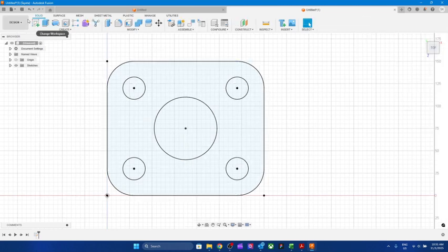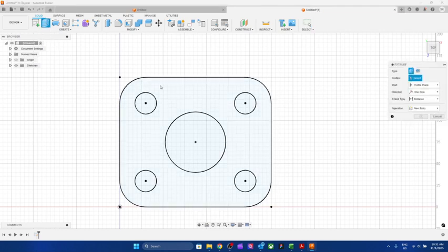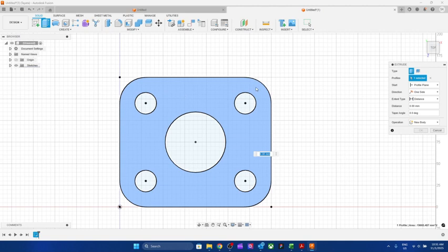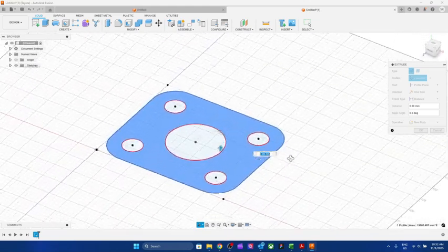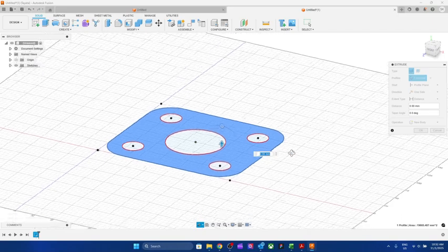Now you're in the 3D modeling phase where you want to enter the depth, how to extrude. So we want to extrude this profile, so directly select extrude and select the profile, but it's flat, I cannot see the depth. That's why I will press Shift and hold it and move with your mouse wheel.